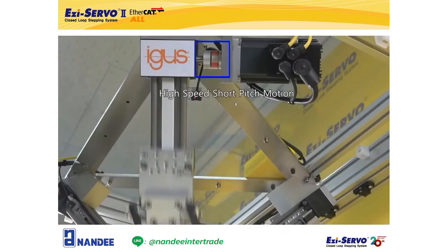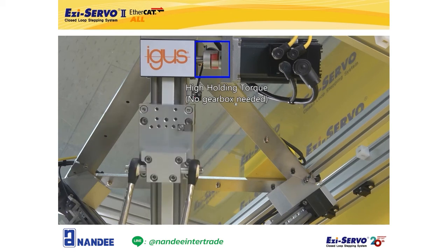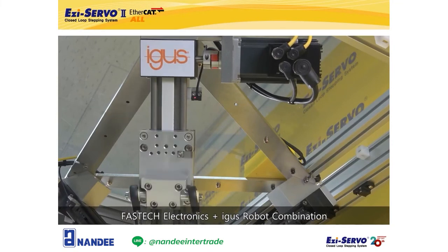The Delta robot of Aegis has a short pitch motion due to its belt pulley structure. It is the characteristic of the stepping motor that generates the maximum torque when stopped, so you can control the Delta robot without a gearbox. Thus, you can directly install the robot to the motor shaft. If you look at the actual motion of the motor, it is operated under the short pitch motion to move the Delta robot, due to the Delta robot's mechanical structure. A stepping motor is optimal for such short pitch motion.